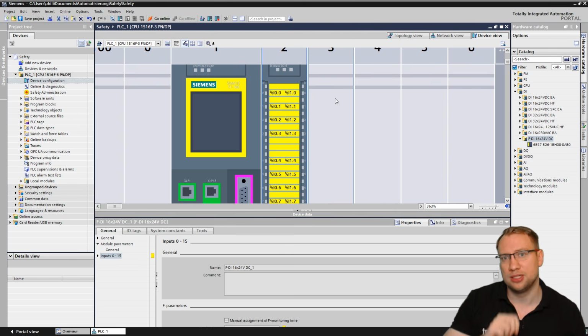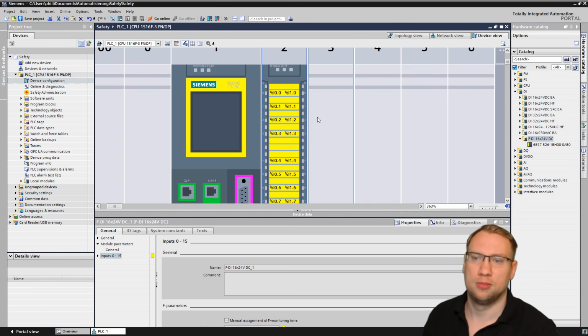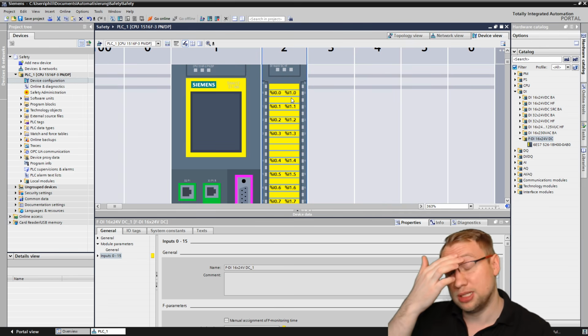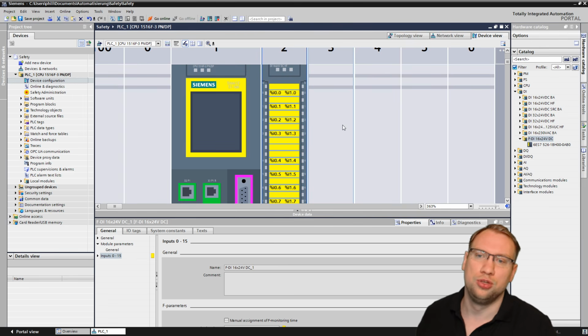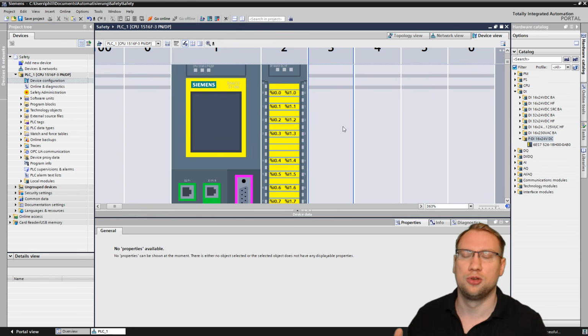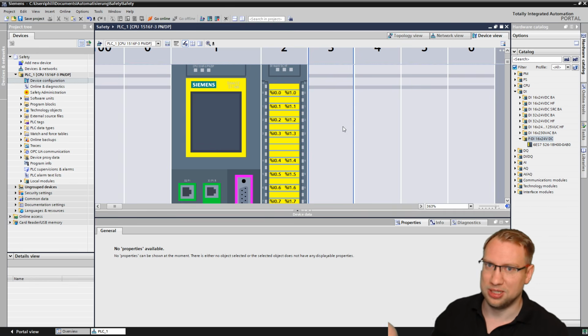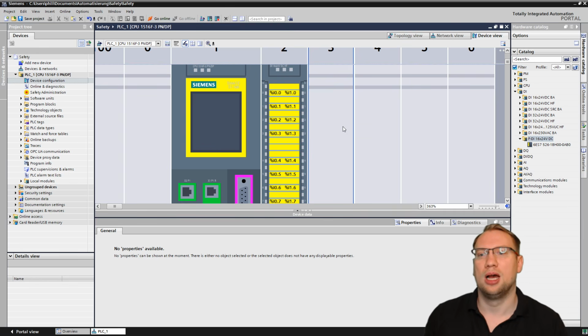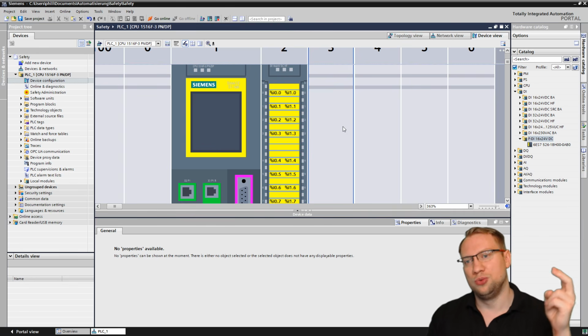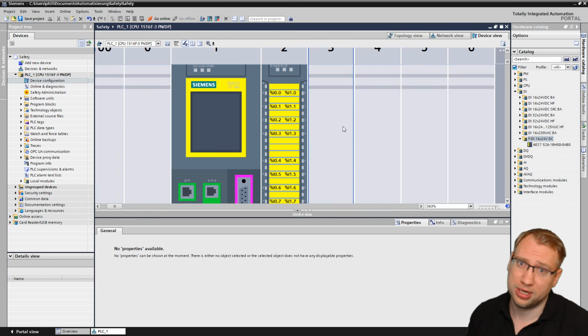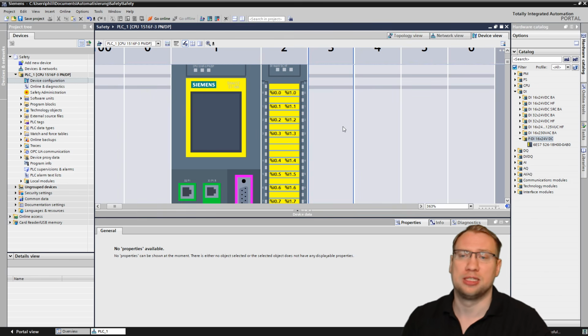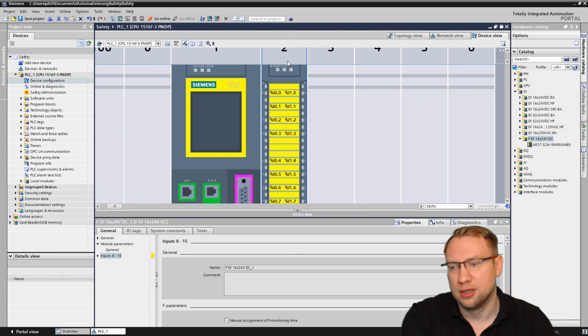Always consider two input channels belonging together. Usually you have safety components that have two outputs, or if you look at the PLC side, two inputs. And those safety components you have to connect to two input channels in order to achieve the best result.